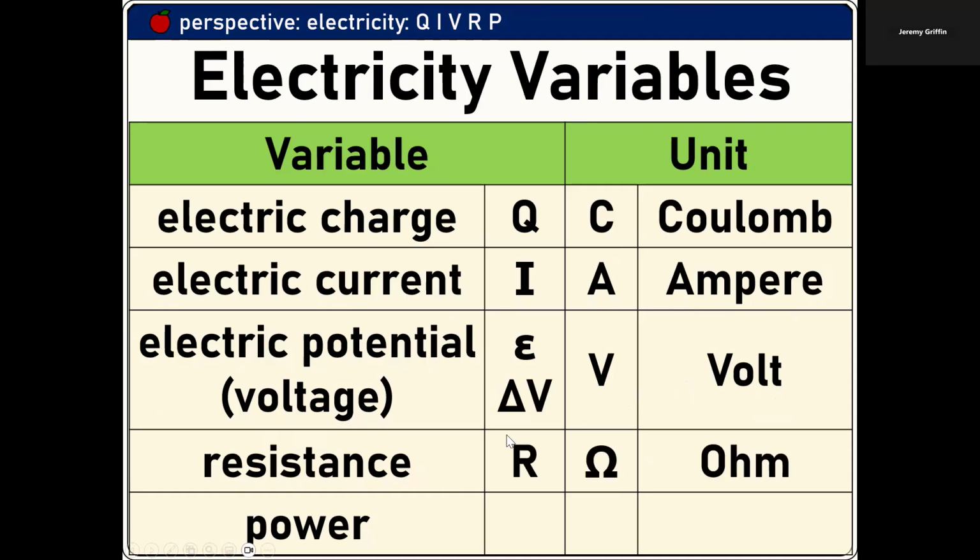You guys notice on those batteries there were 2 leads? Right? So on the 9 volt, there's like those 2 knobs. Right? And on the AA, there was a positive end and a negative end. Right? If you can somehow get a wire to attach one side to the other, then you can get some current flowing. But ideally, you want a resistor in the middle, right? So that it doesn't create what's called a short circuit. Right? If you connect the 2 leads and there's no resistance, then it'll just drain the battery really fast and it'll get really hot. And you can start a fire with that.